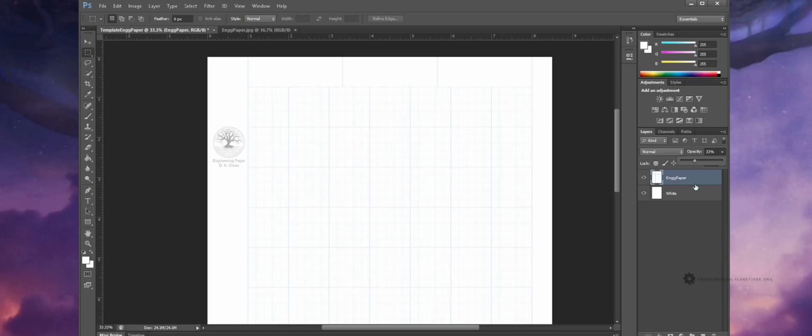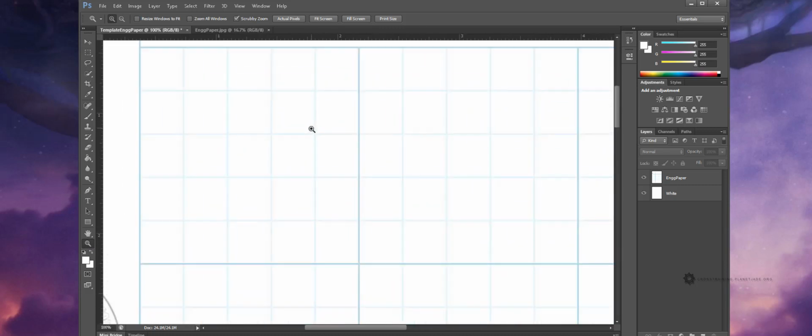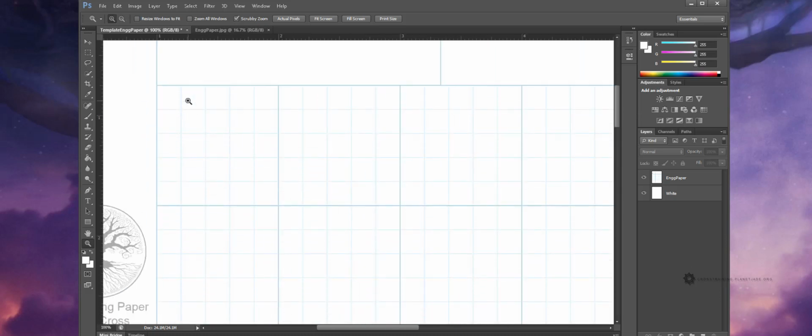And I think for me, visually, I prefer the 33%. So now you can see that all of the grid lines are pushed back, but we're also able to maintain our line hierarchy. So let me just zoom in a little bit. So when you're working on it, you'll probably be zoomed in at this level, or maybe at this level, depending upon what you prefer. And this is still quite workable. You may need to experiment a little bit, like you may need to actually print this when we get to the printing phase, just to see what this looks like on paper if your professor prefers paper submissions. But if your professor prefers digital submissions, you could probably even go lighter, like maybe to 25%.